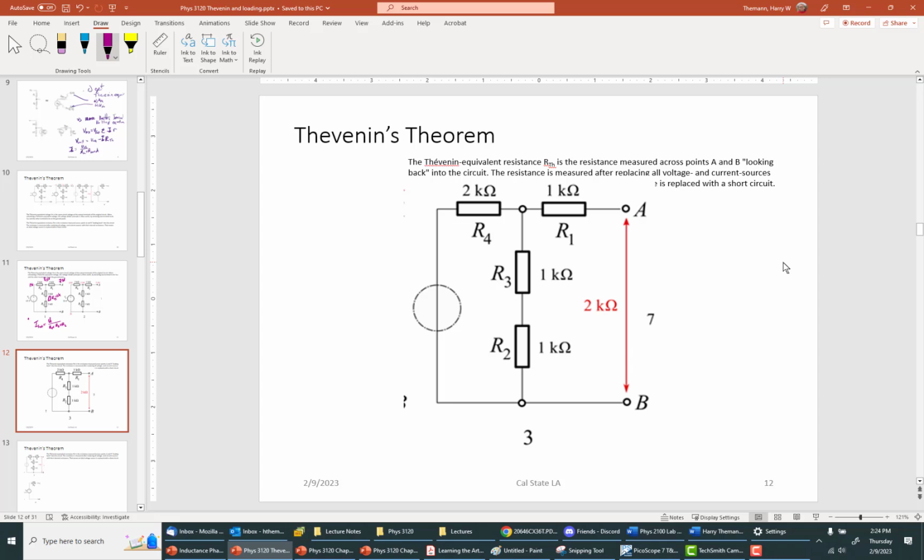Current through, if you like. So it can supply all the current necessary so that no matter what circuit you put on it, it's going to give you 15 volts. Which they do. Remember, we could test it somehow. At some point they run out of gas, but they're not like batteries. Remember, I drew it up there. The terminal voltage of a power supply is flat-topped until you reach some current where it just can't supply it anymore, and then the output voltage just crashes really quickly. So for our purpose, that means that we draw a wire there instead of the power supply symbol.